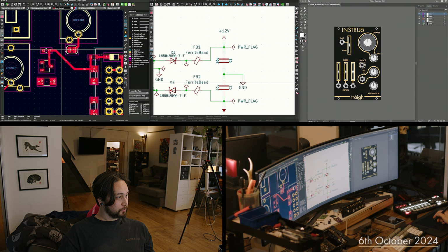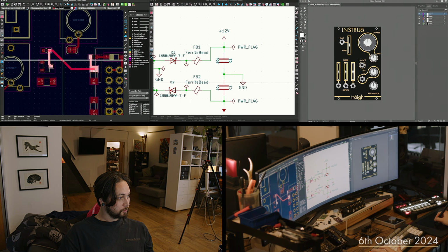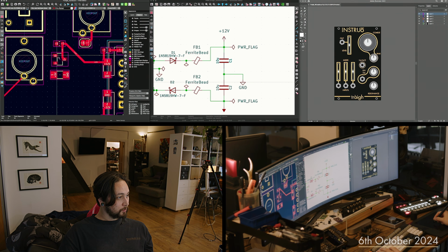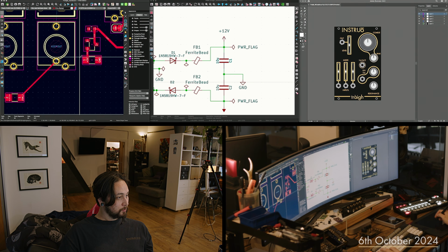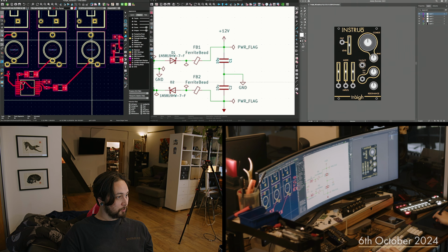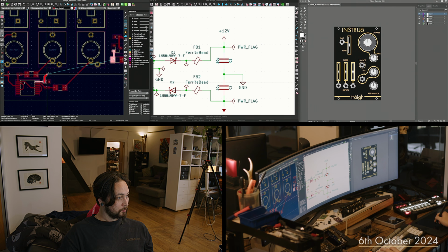That's a 5-volt source going to the regulator that's on bypass cap. Ground. 5 volts there, and this I'm going to bring up and around here. This thicker trace width. Make sure to fully avoid the keep out zone. Should be plenty there.